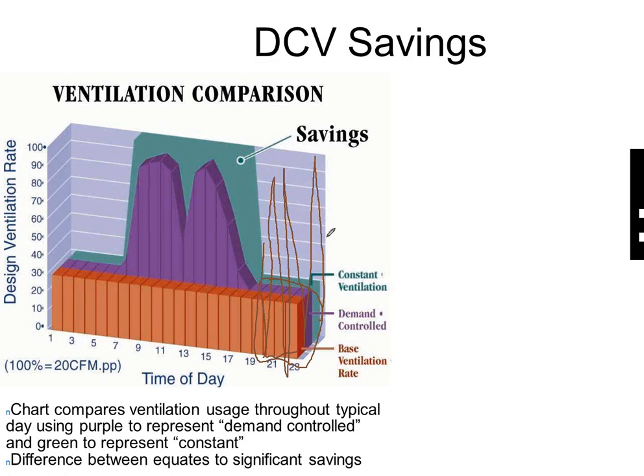Gary's asking what parts per million you are seeing for non-Chicago projects. I'm assuming you're talking about a set point, and a set point is very commonly set in my world at 1150, because most of the time I take a measurement outside and I'm around 450, and 700 above the 450 is 1150 set point. Now, if you're asking about what I just see in buildings when I walk in with a CO2 meter, unrelated to the building having DCV, it's all over the board.